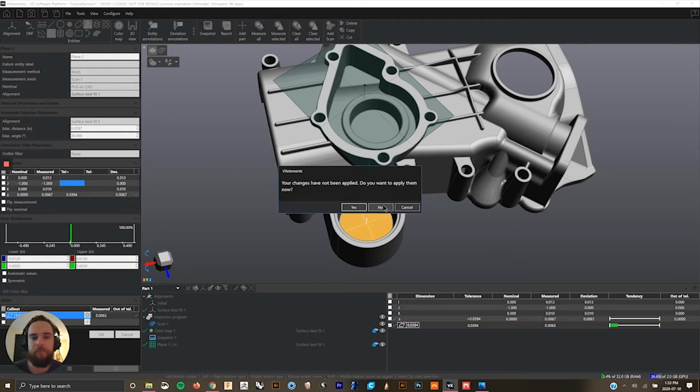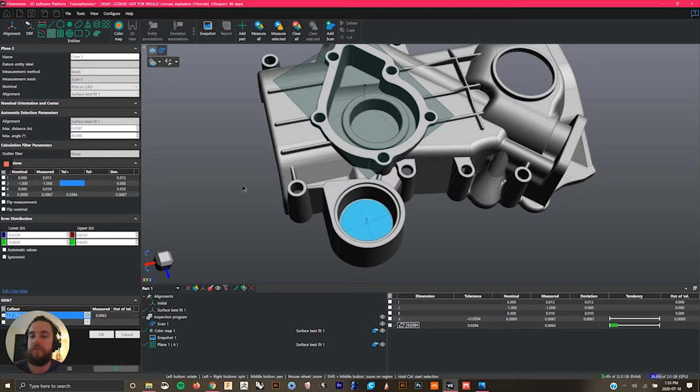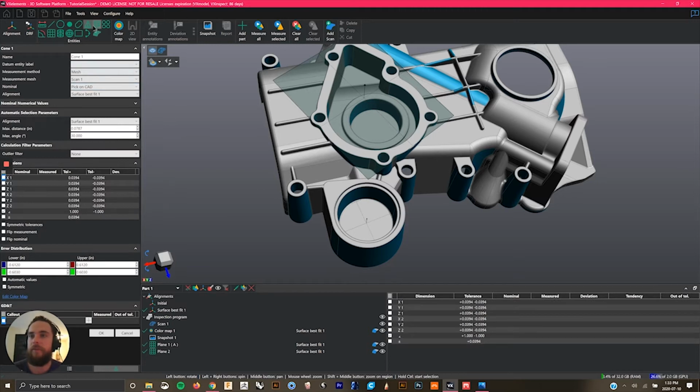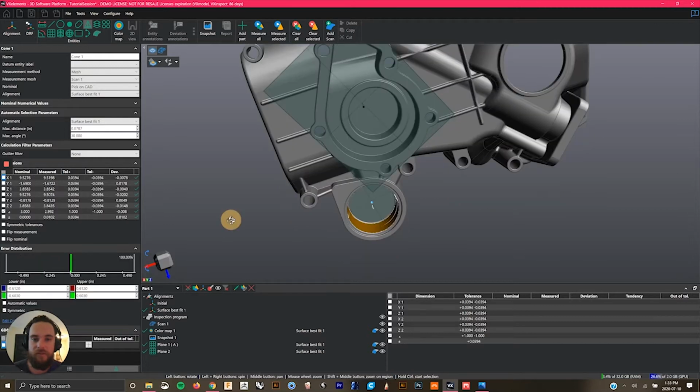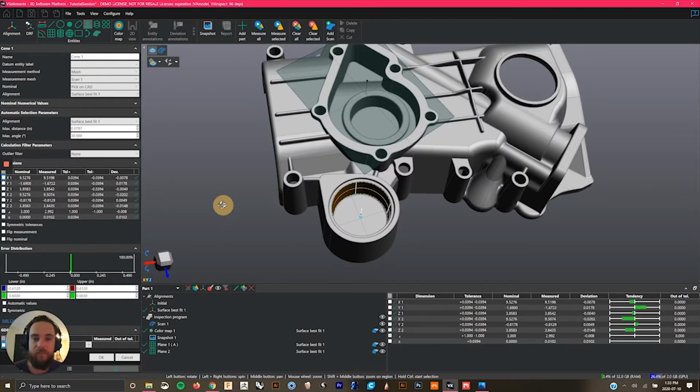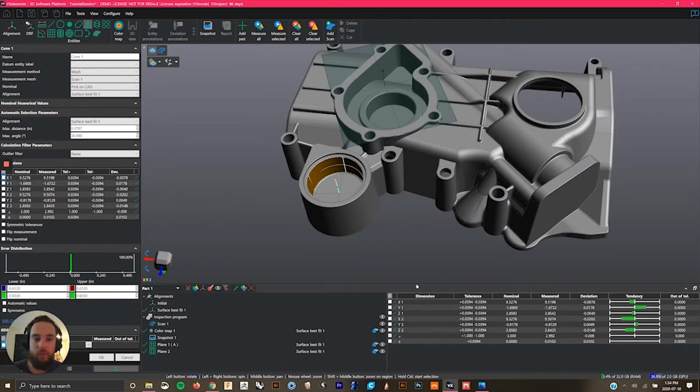And in order to construct a circle, oftentimes you need an intersection of two other things. So I've got a plane at the bottom. I'm now going to make a cone on the inside here of this drafted recession, right? So this cone is going to report out on all these different things. I'm going to, for example, change this so that it reports its half angle out at 0.05.